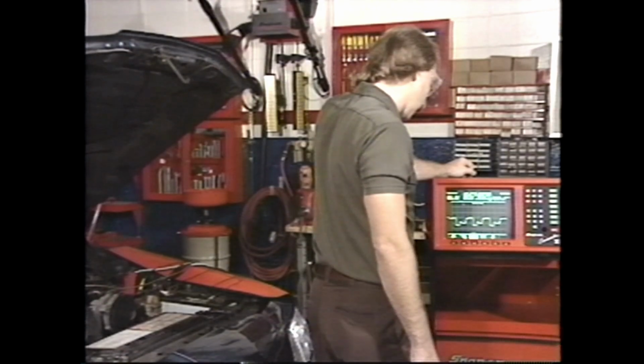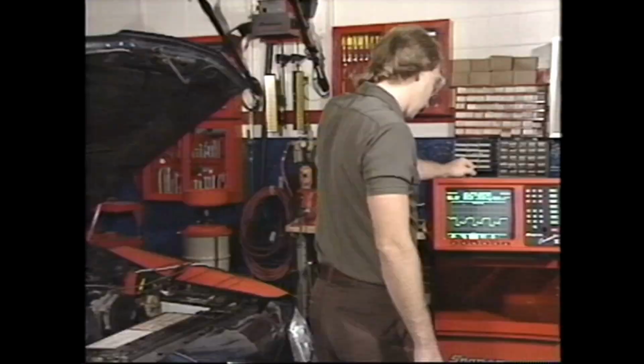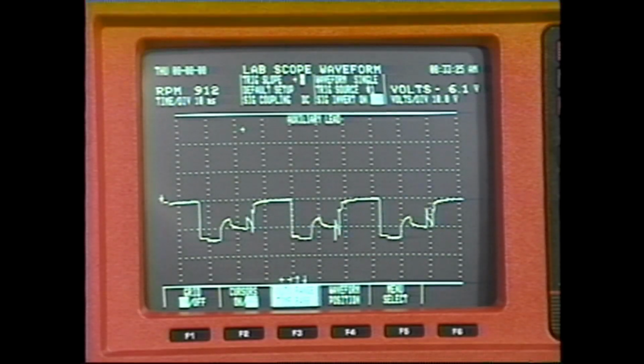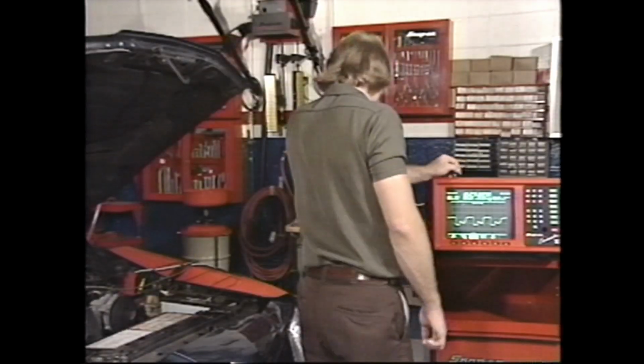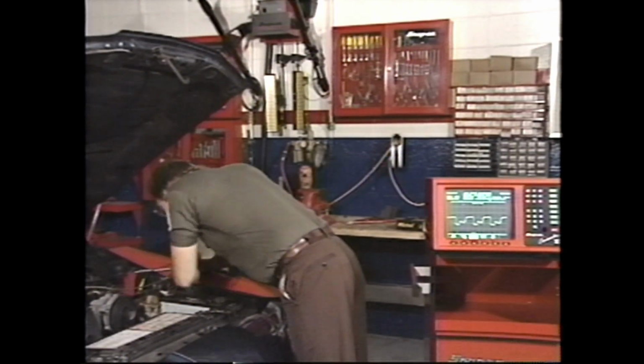Does the waveform look the way it should for the test you're conducting? Is information displayed as it should be? Do you see anything strange, extra or missing pulses, imperfect transitions, noise, etc.? Is the signal coming on at the right time? Is the duration of the signal correct? Is its duty cycle correct? Is the voltage amplitude correct? Does the waveform have the proper relationship to other waveforms on the screen?